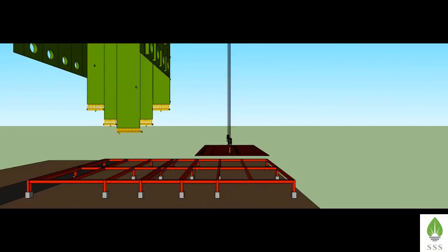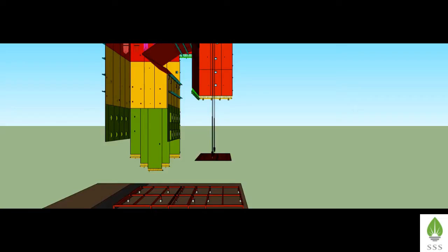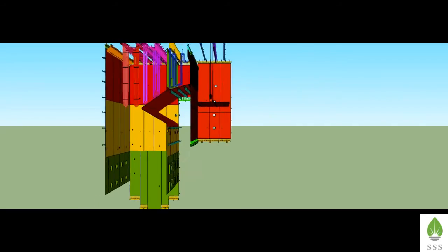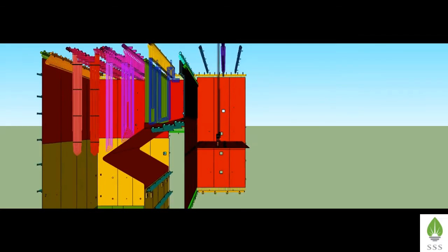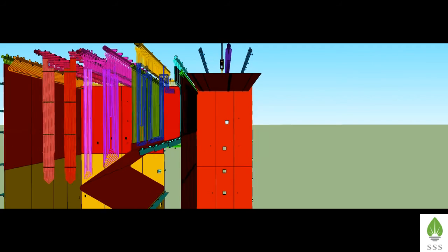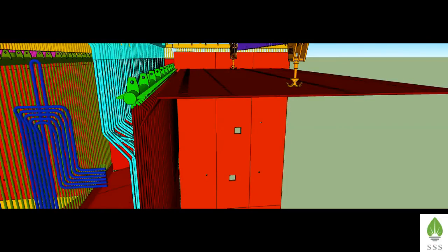Lift the panel using the two hoists supported at both ends of the panel. Weld one end of the roof panel with the stub of roof intermediate header.